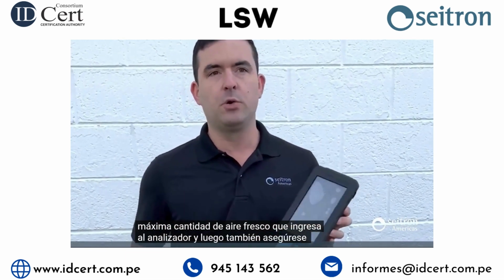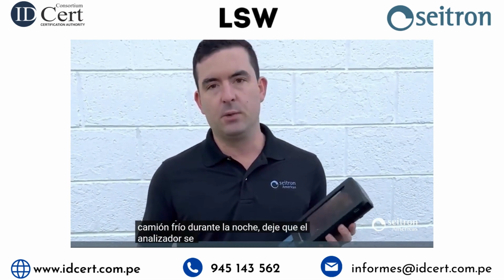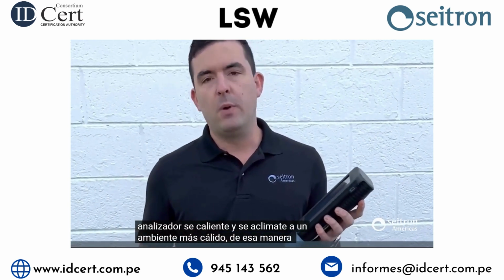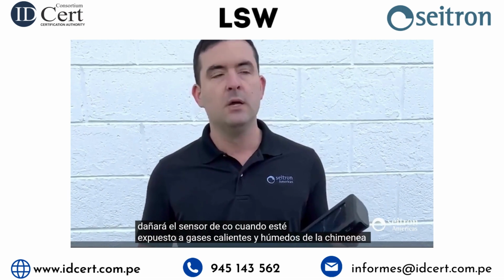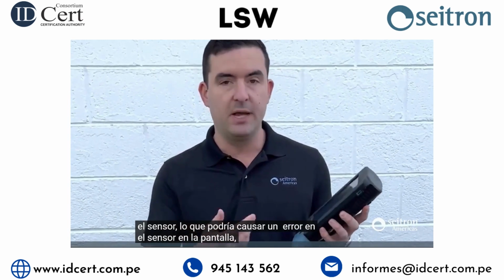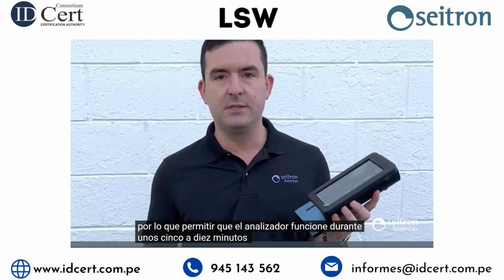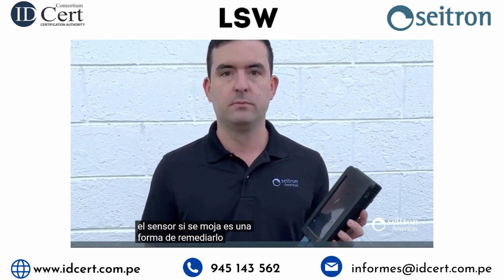And then also make sure that if you left your analyzer in a cold truck overnight, that you let the analyzer warm up and acclimate to a warmer environment. That way you're not going to shock the CO sensor when it's exposed to hot, wet stack gases. That could cause condensation formation on the sensor, which may cause an error on the sensor on the display. So allowing the analyzer to run for maybe about 5 to 10 minutes to dry out the sensor if it does get wet is a way to remedy that.